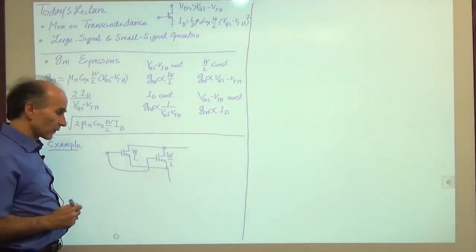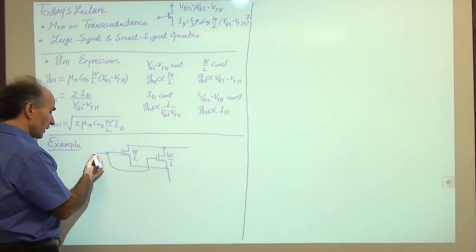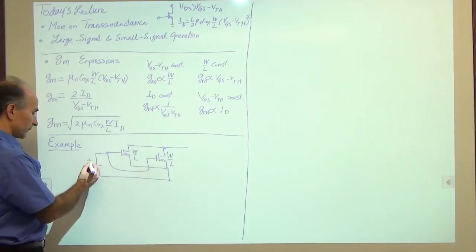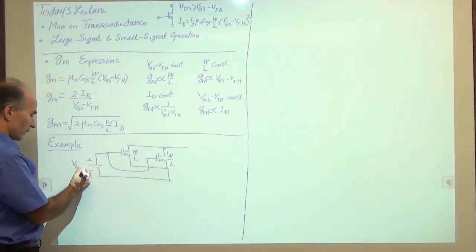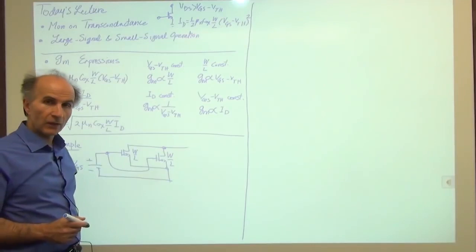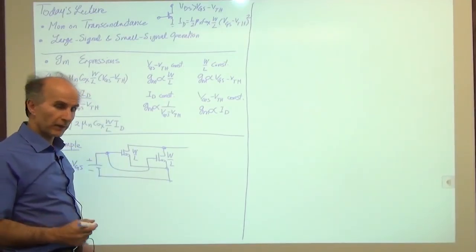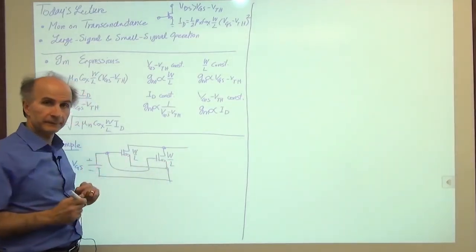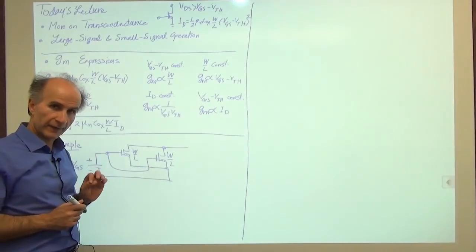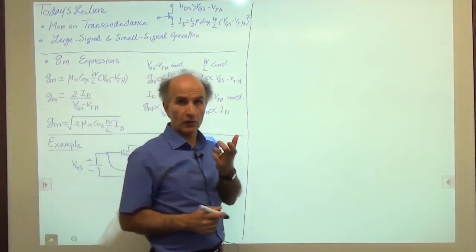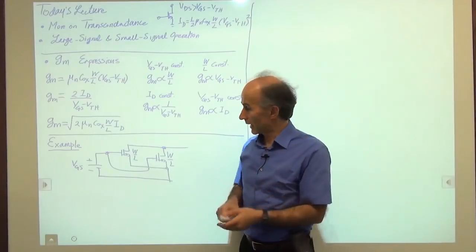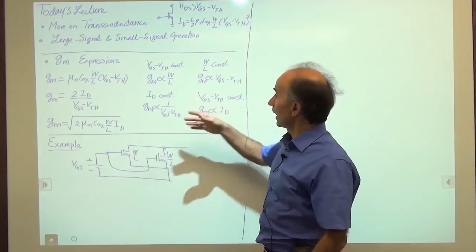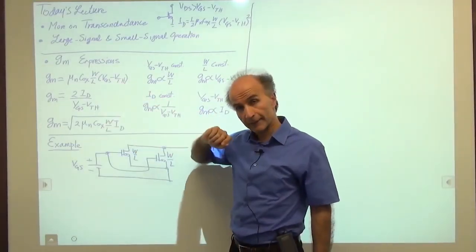All right. So, my question is, if VGS is constant, which means VGS minus VTH is constant, how does the GM of the composite device compare with the GM of one device? So let's think about that for a second. We had one device with a dimension of W over L, and it had a certain battery between the gate and the source. So it has some current, and it has some GM. We can calculate it using any of these, right?